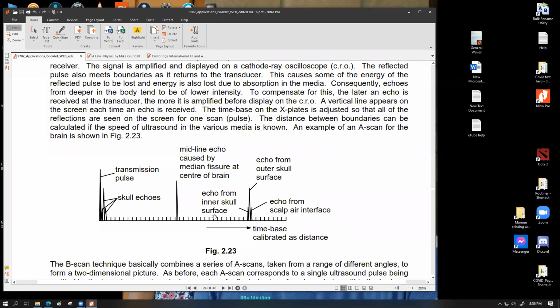and we can find out the exact location of that tumor and how big it is, depending upon the gap between the reflections of the 2 sides of the tumor. If the tumor is really large, then you're going to have 2 reflections on 2 sides which are pretty wide. If it is small, then you're going to have pretty close reflections. So the piezoelectric transducer is capable of picking up all of this reflection information, the reflection of the sound waves, pretty strongly. But the question that you asked, how does that happen?